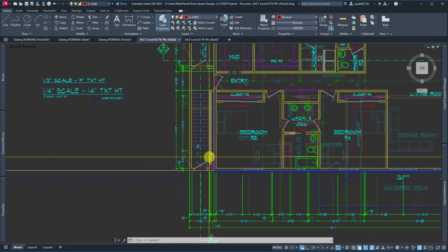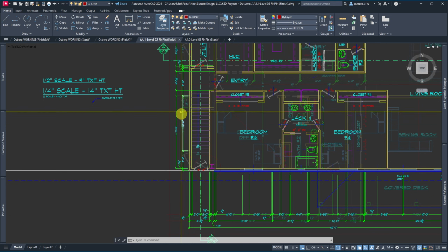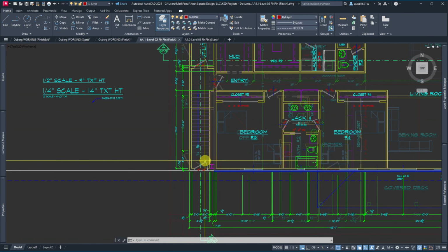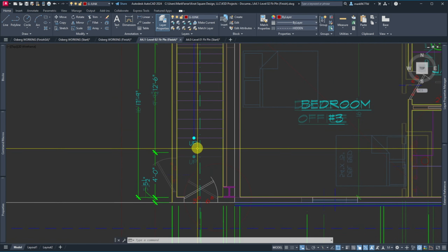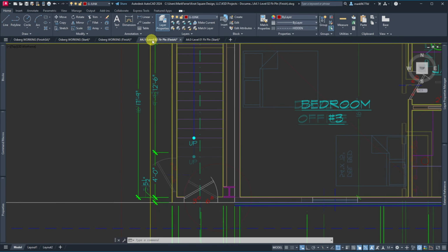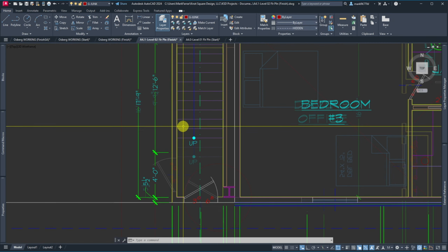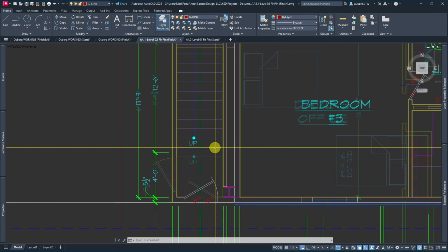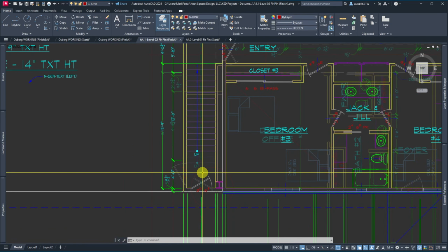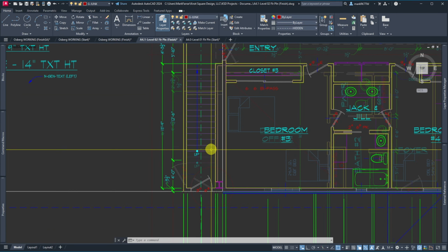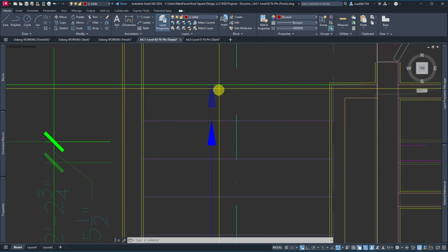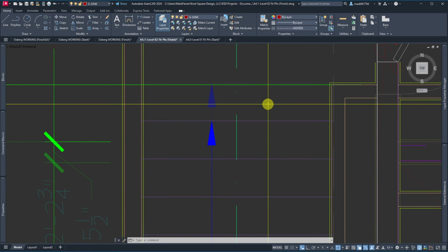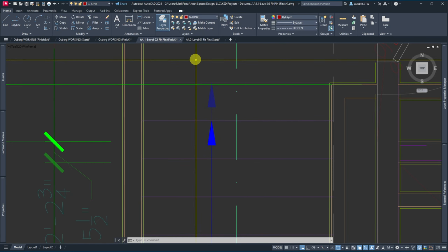One of the things that I had noticed that I hadn't completed in a previous lesson was, if you look at this, you can see there's a fade down below. This is level 2, and that's level 1 in an XREF that's down below. So when we created those stairs in the previous lesson, we had 3 less risers. So 1, 2, and then there's a third here you can barely see. There's a faded arrow from the XREF in the top riser, hidden there. Maybe hard to see in the video, I'm not sure.